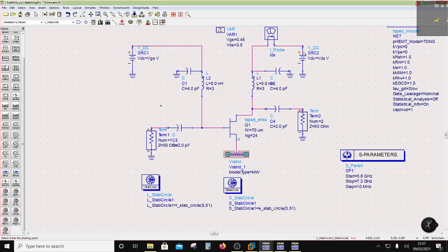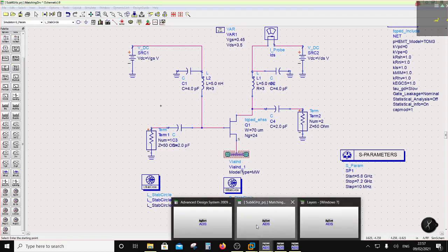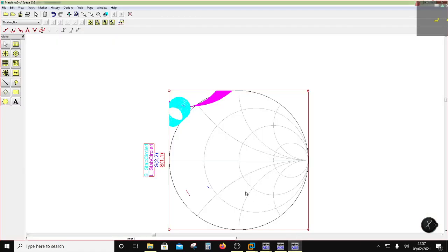They directly put the DC voltage source to the gate and the drain. That is wrong because then you are showing this transistor a short. And if you show it the short, and let's say by chance these circles are over here, then this is an unstable portion and your DC characteristics would be wrong, right?